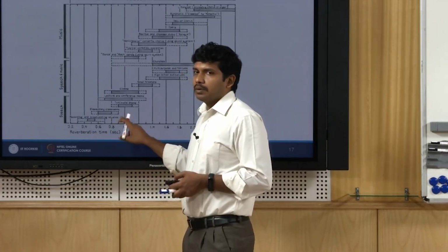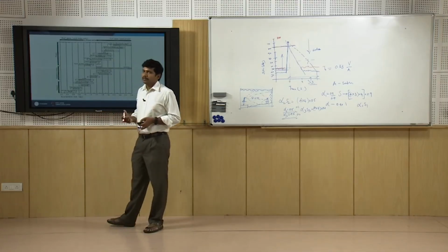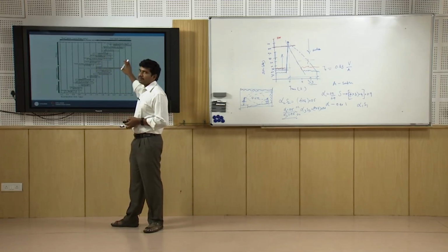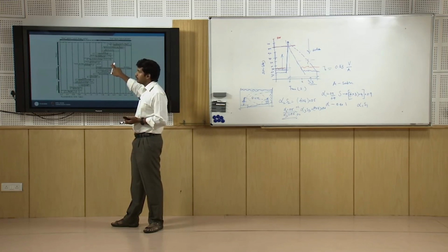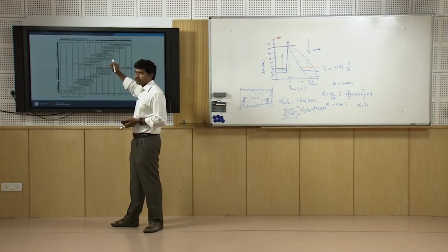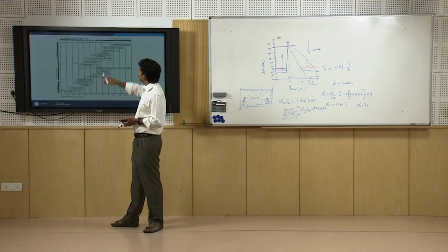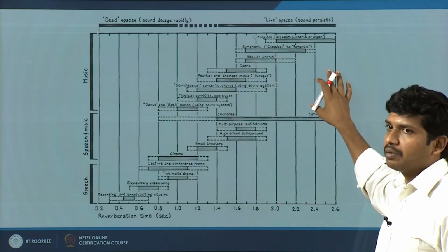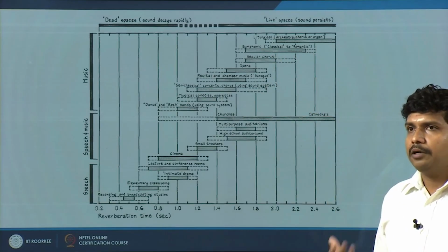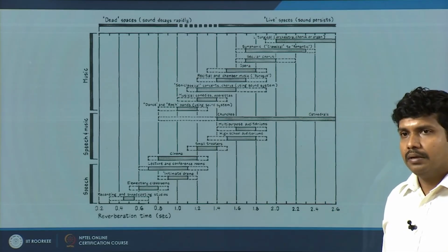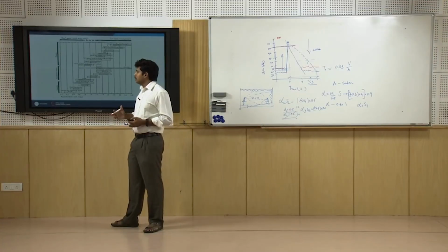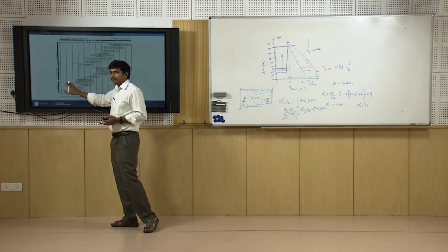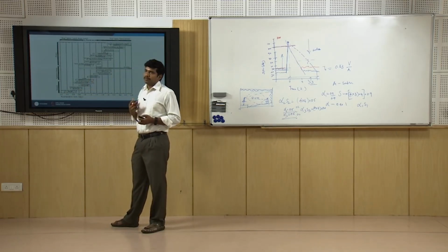Somewhere around 0.8 to 1 second is appreciable even for speech performance, whereas when you have instrumentation playing, it depends, say if it is a violin or a stringed instrument versus a percussion instrument, or a wind instrument, depending on the instrument type and the sound it produces, the frequency spectrum it produces, you will require a different type of reverberation time. So do not try to make the space too much absorptive. Don't put too much insulation material, don't put too much absorption material specifically, so that the room becomes too dead. You have to have a live room to appreciate speech, music, whatever.